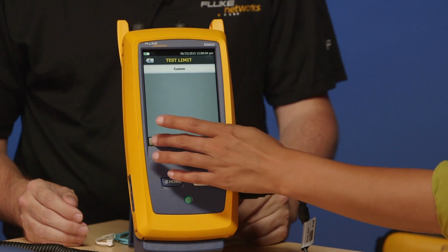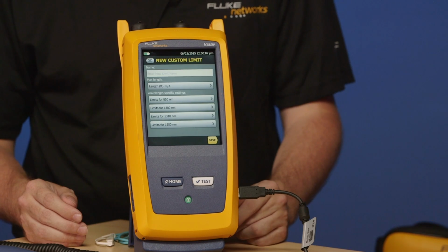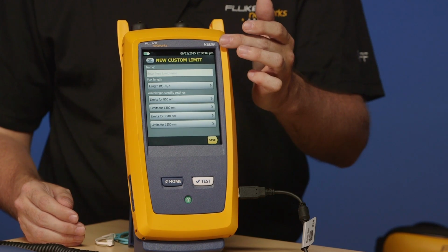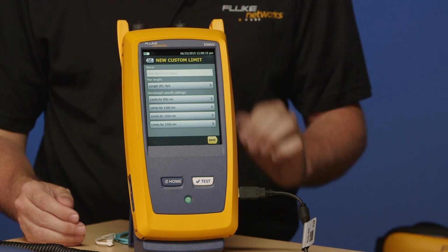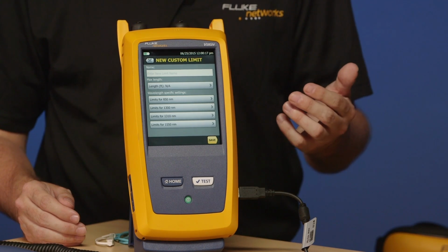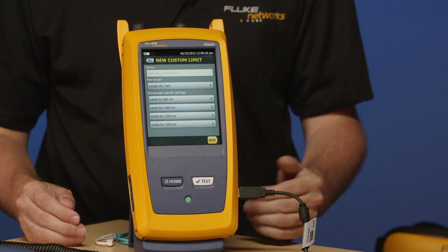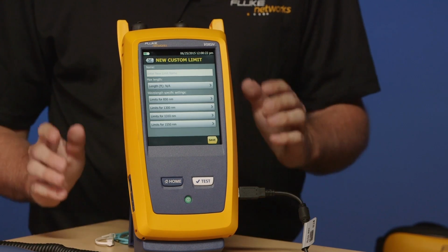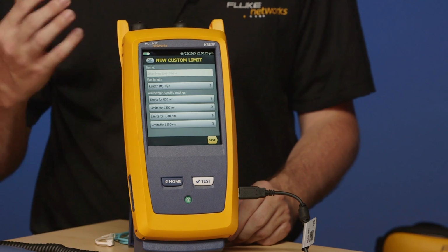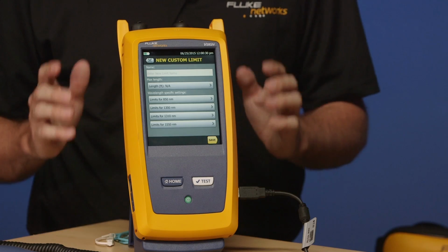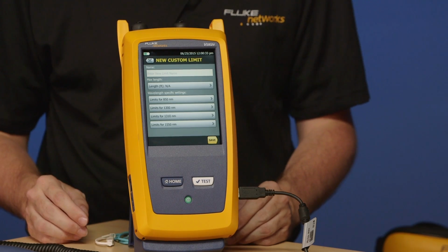With OTDRs, a lot of people like to use their own test limits, and you can do that with the OptiFiberPro. Go ahead and tap on Custom for me. And yep, we're going to go and create one. Excellent. So we can put the name of our custom test limit in the top here, and we have the 4 wavelengths that are supported with this module here, both multi-mode and single mode. So we can go into those menus and add in our connection loss, our splice loss, our fiber loss, and test to a tighter specification. And that's very common with OTDRs, which again is another reminder, please check your test specification. You don't want to be retesting because you selected the wrong test limit.